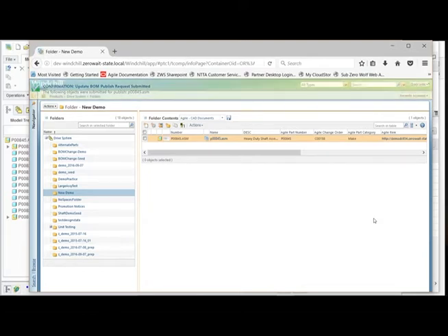And I didn't do anything to edit that bill of materials when I did the save as. I'm using the DesignState tool now to take the changes that I made in CAD and send those structure changes to Agile to update that bill of materials.